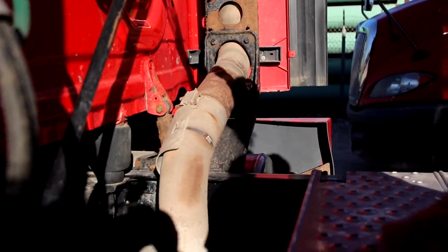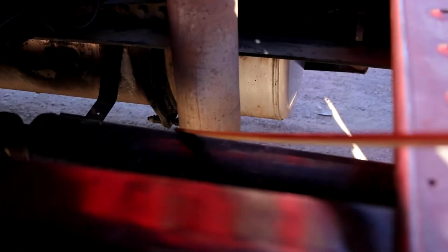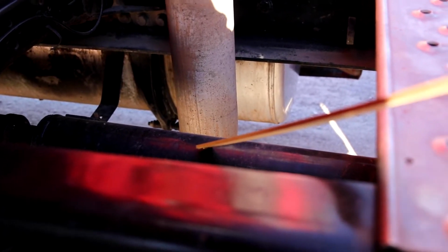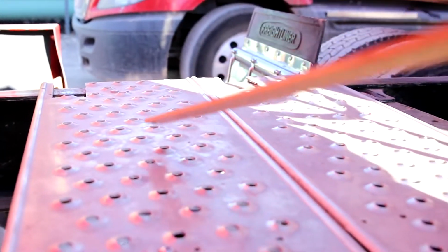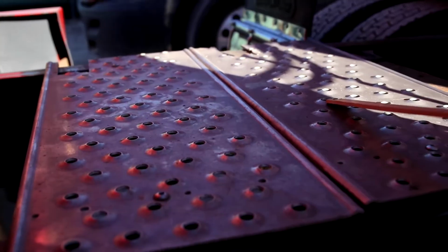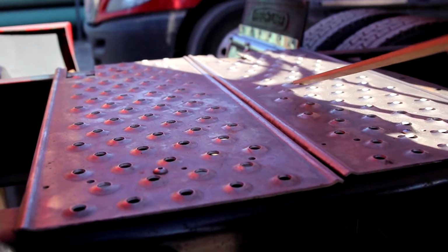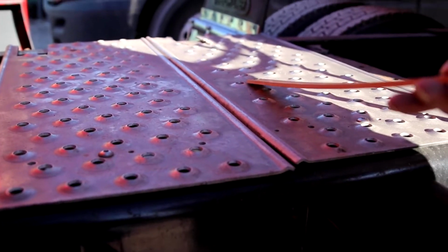Then, this is your drive shaft. It is not damaged or broken, and there is no debris. Then you have your catwalk. Some trucks may have them, some may not. Mounted securely to the vehicle. It is not damaged or broken to cause a tripping hazard.